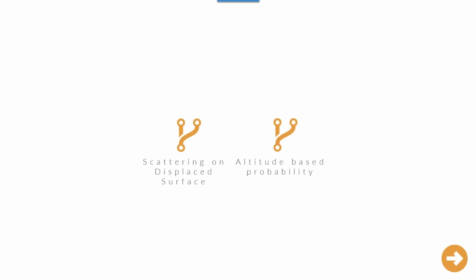So this works great when there's actual geometry in the scene to scatter on. But more frequently these days, people are starting to use displacement for their surfaces. Now, whether that's the whole surface that's displaced from a flat plane or a displacement modifier on top of an existing undulating surface. The problem is that displacement requires the geometry to be rendered or created at render time, and Forest Pack requires the geometry to be created before render time to place the trees. So we need to work around that.